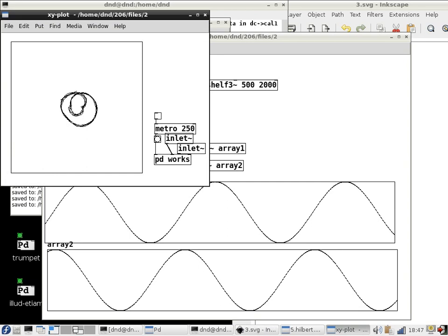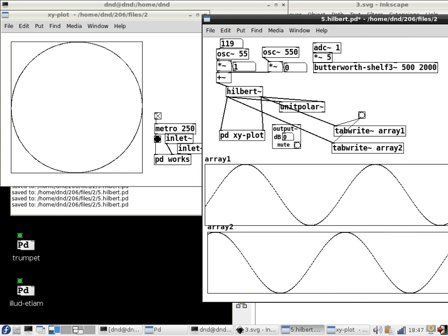Another way of seeing what it is is this picture here. What I'm doing now is I'm graphing 4 times a second these two same outputs, but instead of graphing them in time, I'm making a polar graph of them as if you had an oscilloscope with X and Y inputs and put the two signals in the X and Y inputs instead of having time be X. And now we'll see that actually if we go very slowly, like seriously slowly, like 1 hertz.